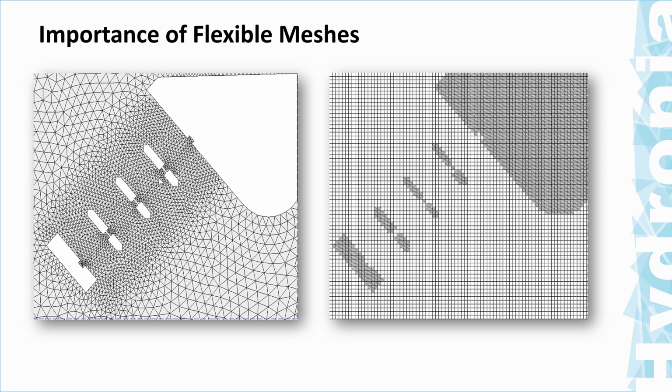There will be gates in between these pillars here, and we are interested in looking at the flow around this area. So with the flexible mesh, you see that the mesh can adapt to this irregular geometry, the round areas here, this very small sections over here, and it can be refined around this area and less refined in other areas where you don't need that much detail.